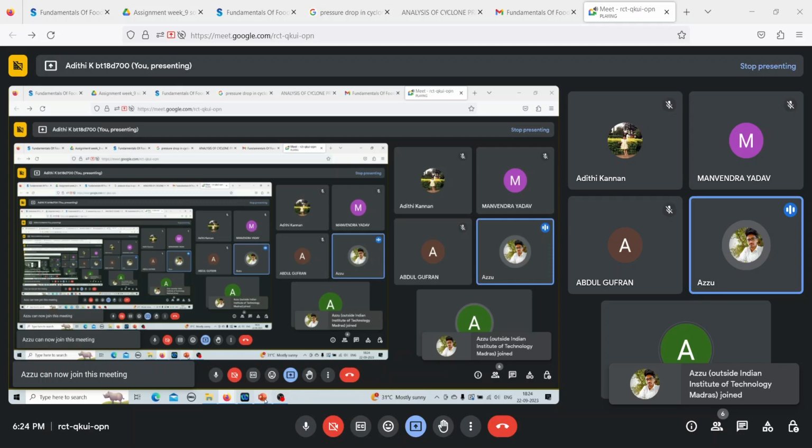So we have the diameter given, we have the speed of the centrifuge basket given. A centrifugal constant is given by v square by g, where g is the acceleration due to gravity, into r, which is the radius of the centrifuge. So v square by g r is known as the centrifugal constant. It's a direct substitution here, but the speed of the centrifuge is given in RPM. We need to convert that into velocity.